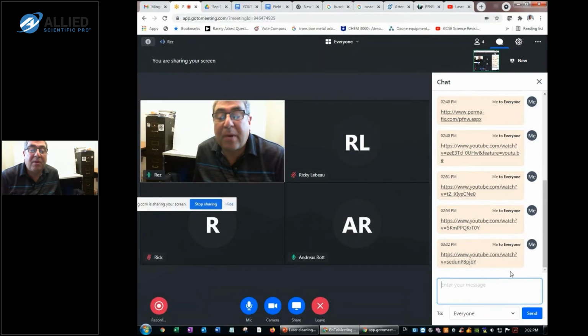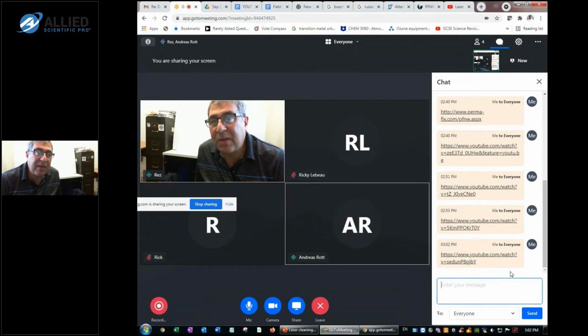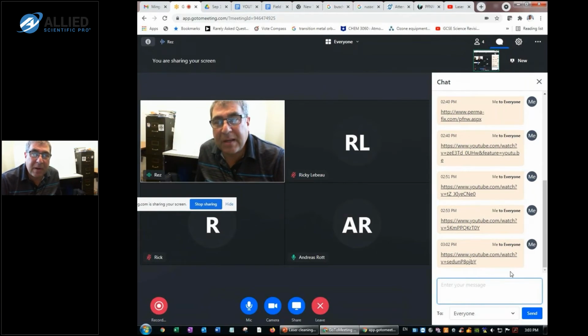You need to adjust the parameters very well, so maybe not use too long pulse width, but at the same time you want to have speed. So make proper adjustments of the energy, the pulse width, and the repetition rate. And our engineers have some recipes for aerospace for cleaning aircraft body parts. So if you send me an email, I can provide you with more information about what needs to be done, what it takes, and what temperature it will reach. Yeah, very good.